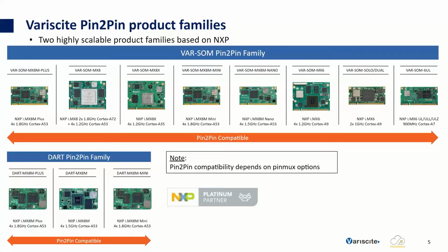Just a quick review of the advantages. We talk about the scalability options. You see our two main pin-to-pin families. One is the VarSOM, the upper one. It's an SO-DIMM edge connector, and you can go from the low-end single core 6UL up to the high-end i.MX 8 and i.MX 8M Plus as well. So a lot of flexibility.